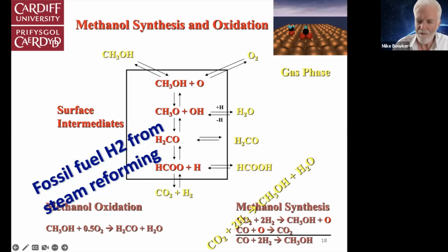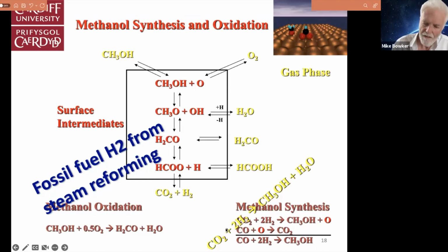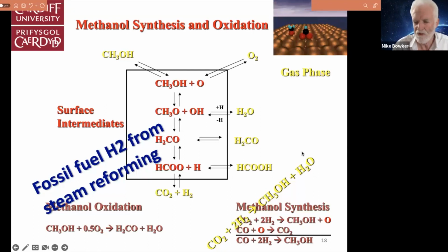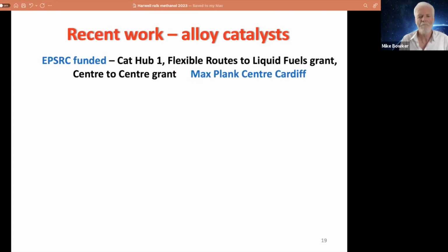Now, of course, that's not the same reaction we're interested in here. Here, we're interested in CO2 and hydrogen making methanol plus water. And I think that says 2, that should be 3 hydrogens there. It makes methanol and water. And that water is a significant player in the whole process and can lead to catalyst deactivation if the catalyst is not made in the right way.